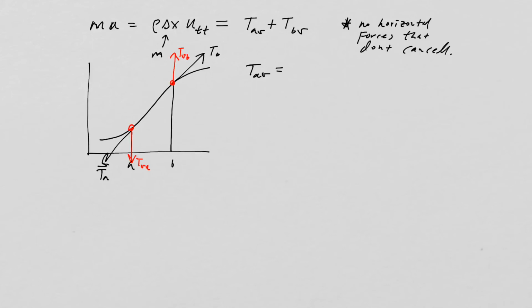It has a force that's going to be equal to TH times the derivative with respect to x. However, look at the slope here. We know that we have to put a negative sign on this one, because positive slopes on the left-hand side yield downward forces, right? So we're going to have to negate that.